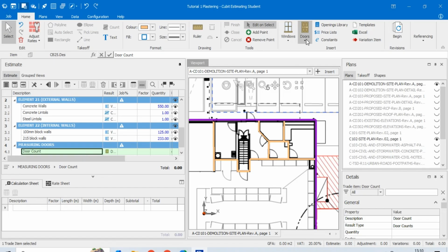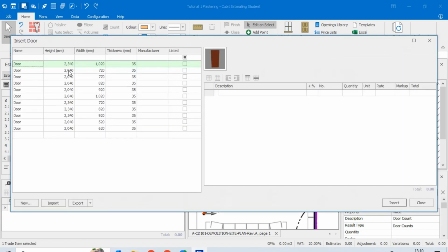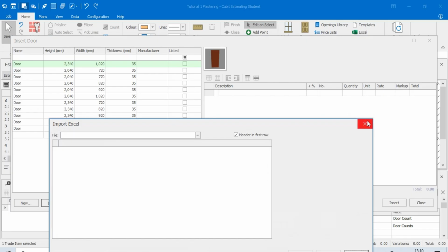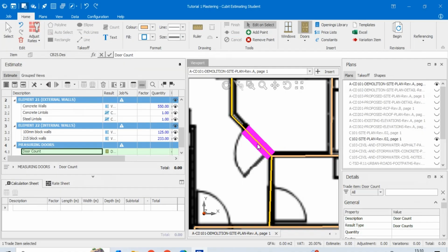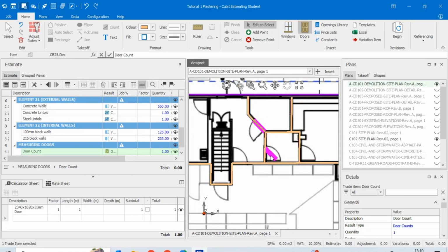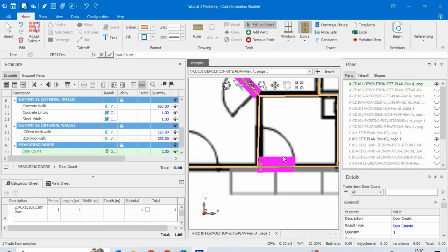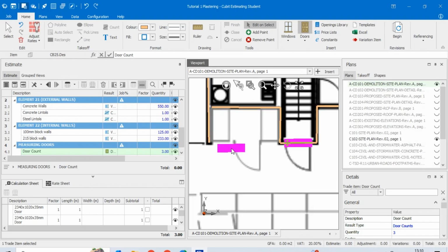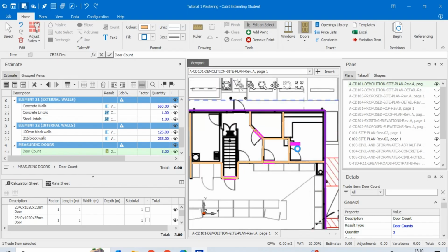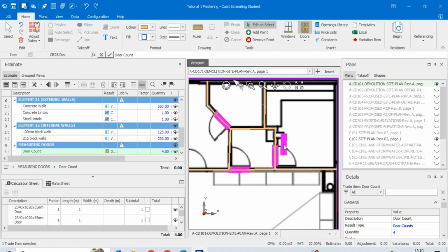And if you don't find yours, you can import. You can import maybe a door from Revit, or you can just insert your exact specifications. So yeah, here you have the correct size. You just select on a line that you had already measured. So that is where you add the door. If there is no measuring line, the door will not detect. Like in here, we have to add this internal wall so that we can add the door.